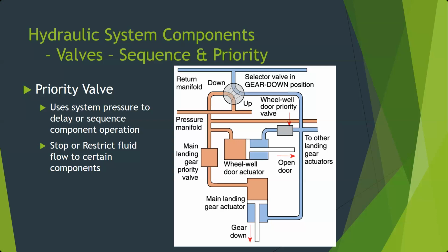And you've seen this happen where when we actuate things on the 727, if you actuate more than the pumps can handle, or if you actuate it quickly, you get a drop in system pressure, right? So the pressure is a little bit lower when there's somewhere for the fluid to go.